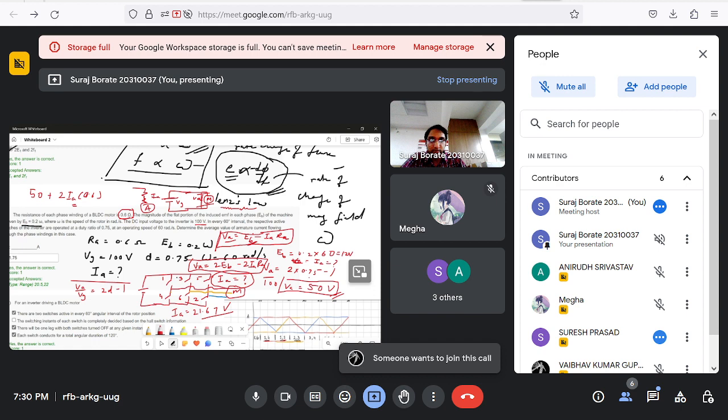Okay, on drones also we use BLDC motors, but those motors are not flat motors. Okay, those motors are taller motors where the height is more and width is less. Whereas in the quadruped robots that resemble legged robots, like Boston Dynamics dog and all, there they use flat motors. Okay, why? Because the number of poles is higher.